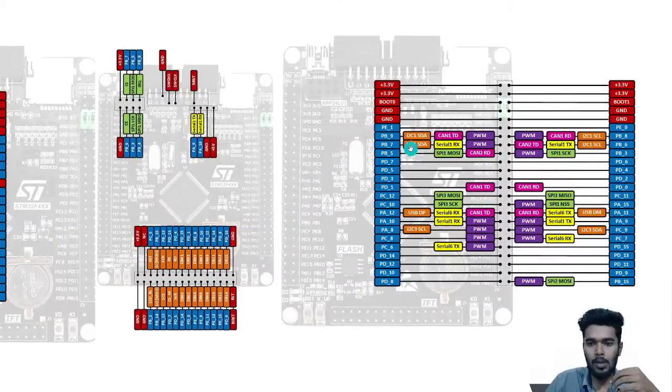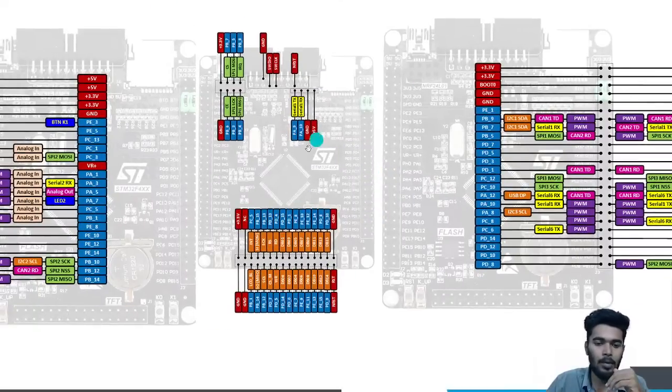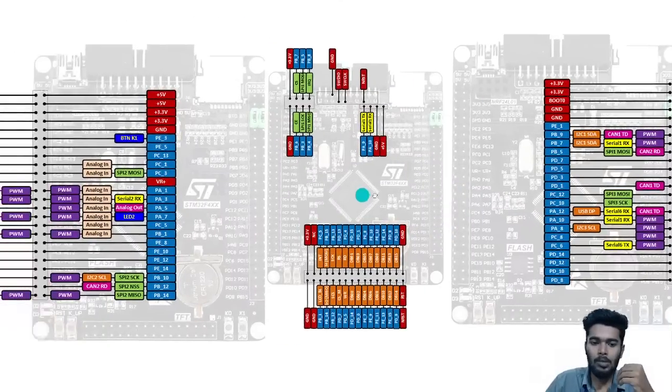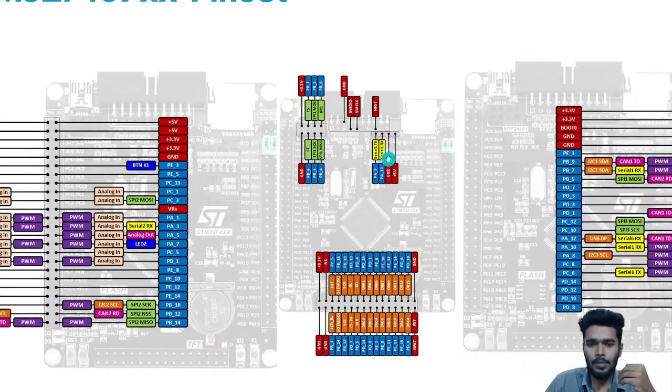4 functions. You can see I2C, CAN, PWM, and another one is GPIO, general purpose output, which means you can also use the pin as a GPIO, for processes like blinking an LED. So first of all, you have to know about the pinouts. We have 100 pins here. We have ports up to H, which is 5 ports.